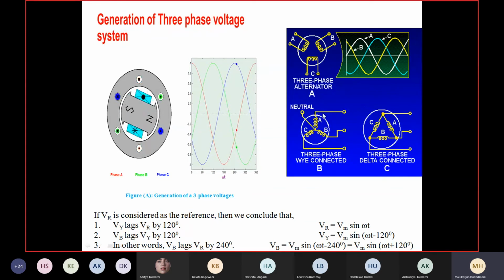Then with respect to current, whatever is the current entering the line or leaving the line is called line current. From the terminal perspective, from this machine going out or coming in, that is called line current. Whatever is the current coming out of or going into the phase, that is phase current. Whatever is coming out comes out here, whatever is entering here enters here. I mean to say line current and phase currents are one and the same in star connection or Y connection.